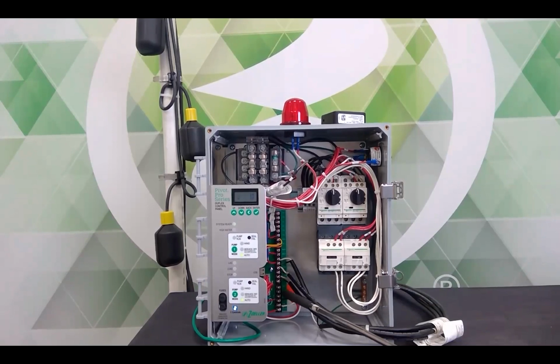But you also have right here dry contacts. The dry contacts on this board are for any alarm that's created. Any of them will change the state of those contacts. But the contactors themselves for the pumps also have dry contacts. So you have basically 3 sets of dry contacts. You've got alarm dry contacts and you've got pump run on each contactor. So you just bring a pair of wires from those into your BAS to do your monitoring.